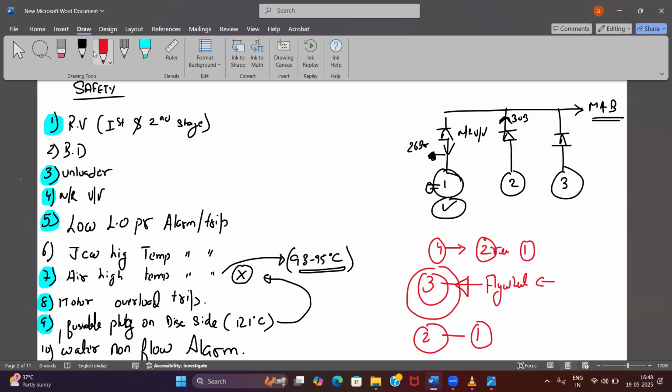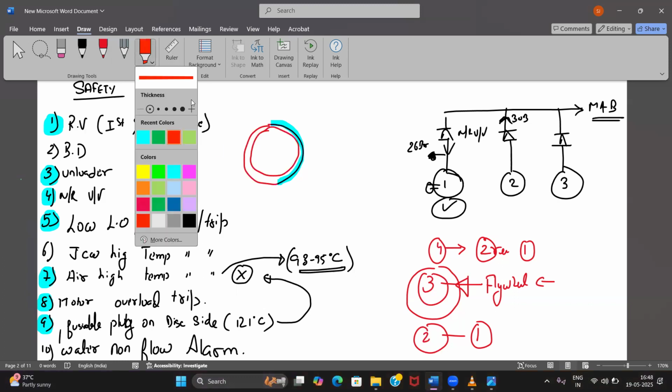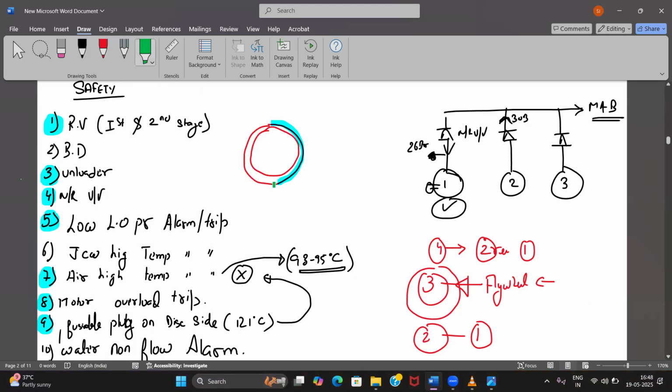If I take this example, let me explain one thing. Suppose this is a 4 stroke engine and this is one cycle, and this is the second cycle of the complete revolution of my crankshaft. I have the power stroke only up to this much. But for the remaining cycle, who is supplying this power? Flywheel. This power is completely supplied by the flywheel. So comparatively, I need a bigger flywheel for this much.